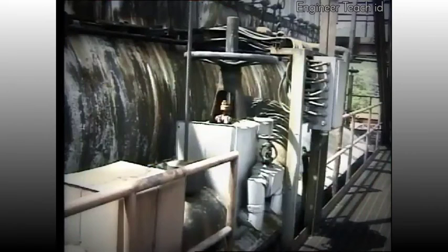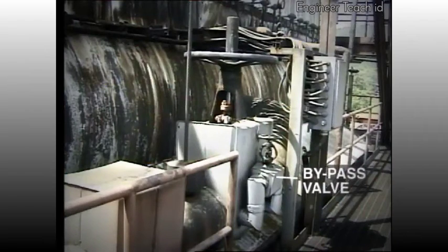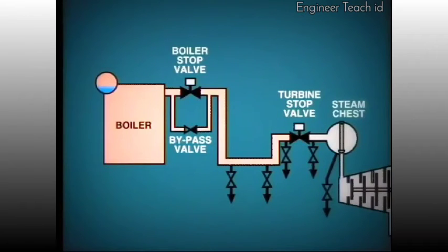To overcome this problem, 1 or 2 small bypass valves are fitted, say 1 inch in diameter. Due to the much smaller face of this valve, it can be opened to allow steam to enter the main steam line. Initially, this steam line will be cold, and the steam will obviously condense. This condensate must be removed through the drain lines, which are fitted at low points on the line, including just before the turbine stop valve.